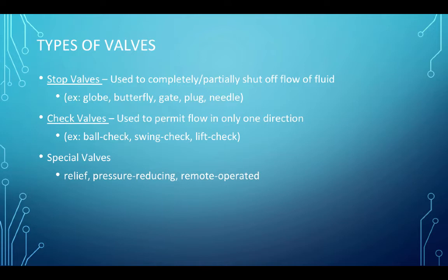And then there's a special category of valves: remotely operated, pressure reducing, pressure relief valves. These are used to control pressures and or flow on either side of the valve by a variety of springs and diaphragms. A pressure reducing valve is functionally equivalent to the regulator in a scuba system.